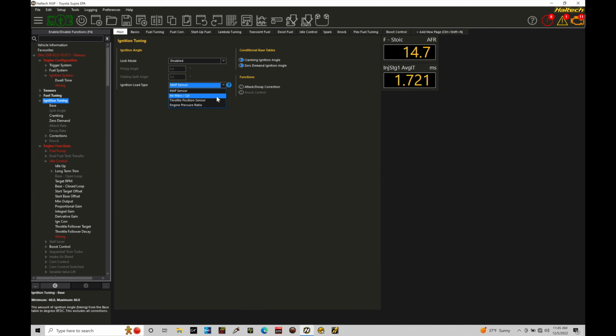That's if we're tuning with a mass airflow sensor and we don't have a MAP pressure sensor hooked up at all to our Elite box, which I highly recommend that you do, even if you're tuning with a MAF. It gives you another point of reference in terms of load registration. So you can choose air mass per cylinder. You can choose throttle position.